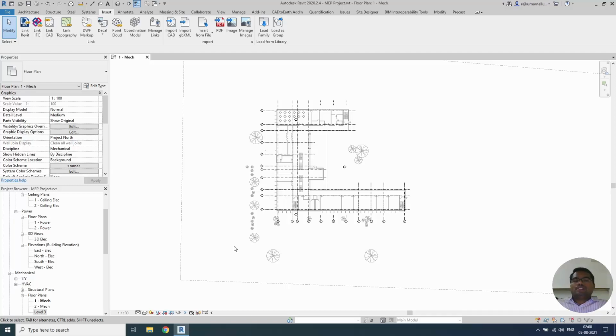The future will be like that, but at the moment Revit does not support maximum size files. So to reduce the complexity and the size of the project, we will be segregating the model based on the discipline. If required, we will be segregating them based on the level. It is based on the project requirement to reduce the file size.